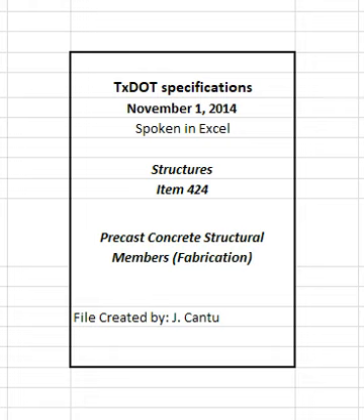Correct members not meeting these tolerances at no additional expense to the department, to achieve a satisfactory completed structure. This also includes costs for correction due to variations in vertical beam camber. Correction may require replacement of the member. Horizontal misalignment, sweep, in beams, which may increase at a later time and exceed the tolerance shown in Table 3, may be acceptable if the members can be hauled, erected, and aligned to within the allowable tolerance without being damaged. Store these members in a manner that will minimize the sweep.